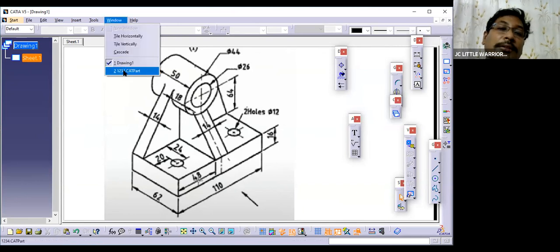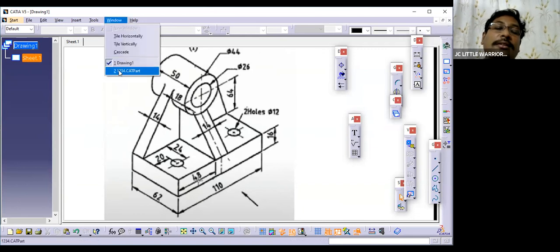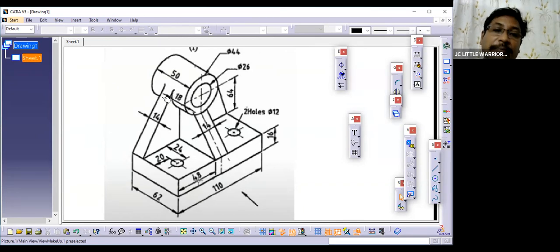So if you are using this stiffener option, then always consider that at the mid of this, and then it takes thickness both sides. Okay, please remember that. So that's the reason we need to consider neutral fiber. Okay, this neutral fiber is at 7 mm, that is from this face 18 plus 7.